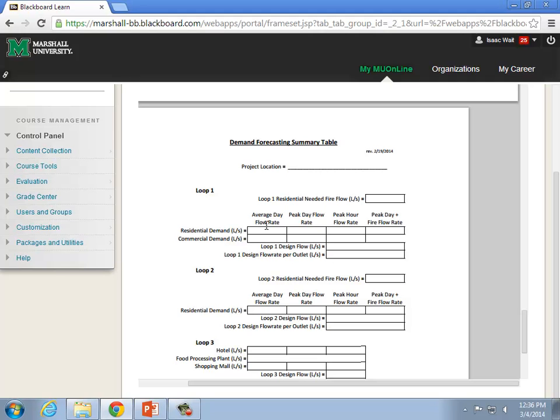Even on the average day, the flow rate is varying over the course of the day. It goes down at night, up during the day, down again, high at night. So if this is midnight, 12 a.m., and this is noon, and we're back to 12 a.m. Even on the average day it fluctuates, but there is some average daily flow on the average day. Now I'm saying average twice. I hope that doesn't confuse you, but you're talking about the average day of the year, and the average flow rate during that average day. Any questions so far?